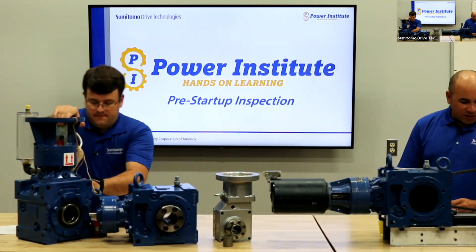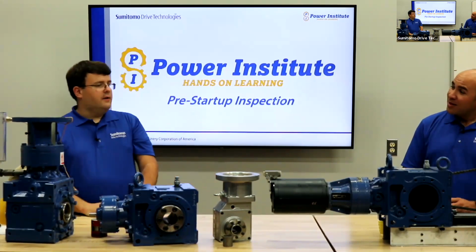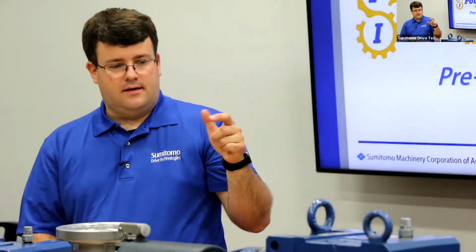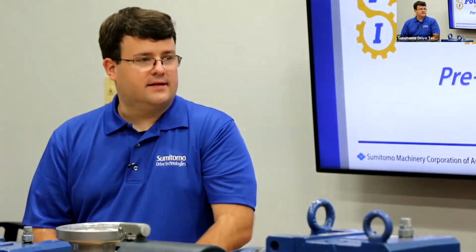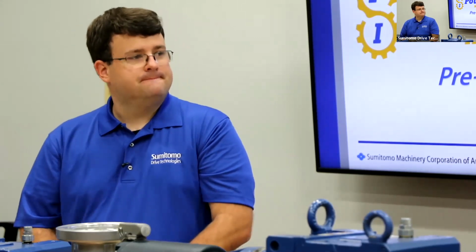Another question: should you also consider lagging in the pulley diameter in your formula? Yeah, I would. In general, I would say yes. It's thin enough that it doesn't affect the calculation very much, but I would do it as general practice, because it does change the overall diameter. Okay, gotcha.